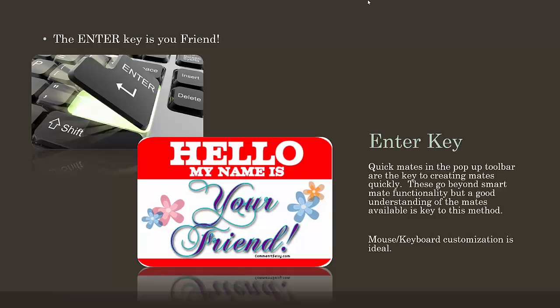No, no. The copy with mates has the specific button for alignment. If you do the copy with mates, there is a box where it says default, which is going to pick whatever's closest to it, or you can actually say align or anti-aligned on there. And I think there's a fourth function that I look at and I'm like, whatever. It doesn't make sense why that fourth function is there. Yeah, they can sometimes turn. Yeah, yeah. So the smart mates, no, sorry. Yeah, no, smart mates. I'm thinking mate references has that option. I don't know. I'll have to look into it. Something that I can look into.